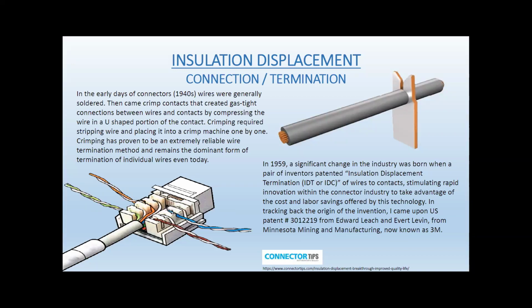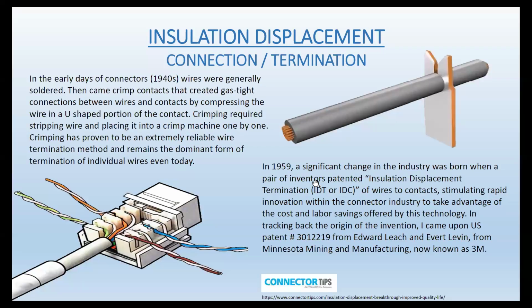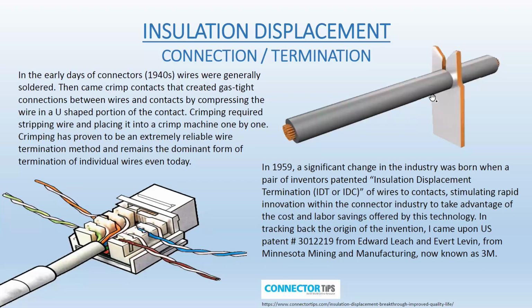Insulation displacement connection. I keep explaining that during the labs. So here you can read that a little bit. One thing I'm going to mention, and I was going to correct it, but I decided to keep it so I can explain things. The insulation displacement connection, in short, is a connection made by the connector biting into the insulation and making contact with the copper conductor. For that, we need to position the conductor on top here and use a punch tool to push it in.